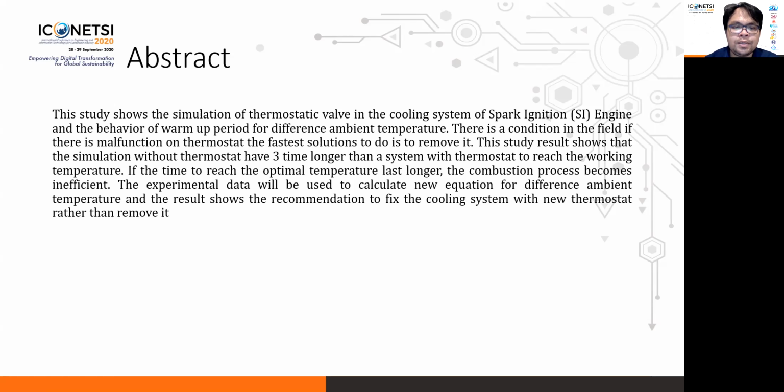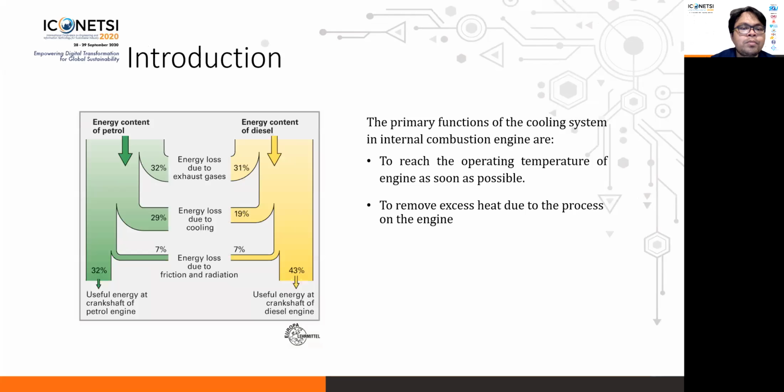There is a condition in the workshop on the field. If there is a malfunction in the thermostat, the fastest solution is to remove the thermostat. So with this study, I want to show that if we do not use the thermostat, it takes longer than a system with the thermostat to reach the working temperature of an engine. I use experimental data, a simulation, and also a mathematical equation to solve the problem.